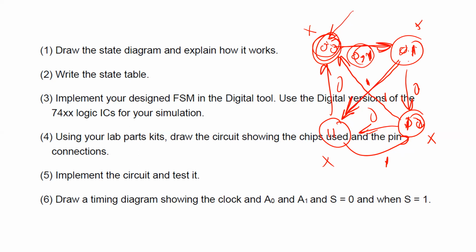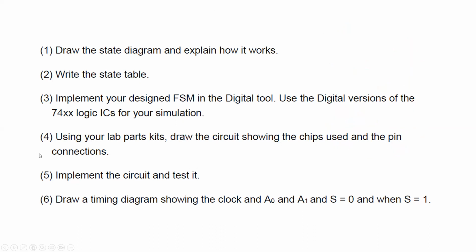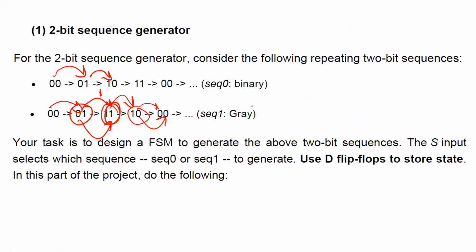Guys, try to spend some time on this one, think about it very carefully. And then after that, you can just look at the examples you have in the slides. Anything after the state diagram is just straightforward. Number one, you have to translate the state diagram into a state table. That's very easy. Once you do that, you need to implement it using digital tools, and you can test it. It's very easy to test.